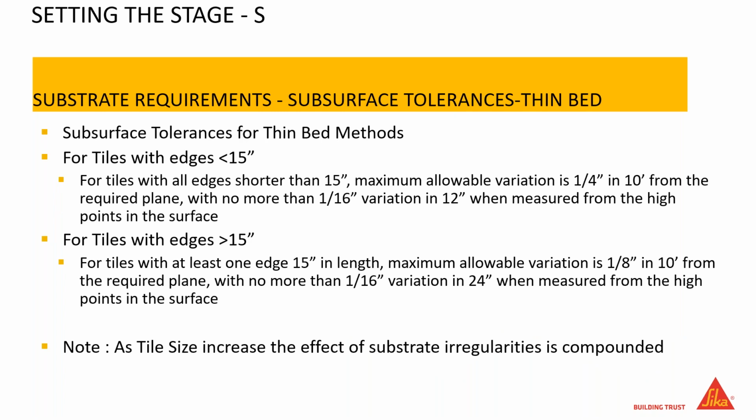So now in this S for substrate, we are looking at, again, not only for that deflection in the wood substrates, we're looking for that substrate tolerance flatness on the concrete substrate. So that kitchen area is going to be probably a fairly large area. We want to know, A, what type of tile we're using, so that I know, do I need to be in that 1/4 in 10, or do I need to be, for a large format tile, at that 1/8 in 10? So again, these are questions we don't know yet.